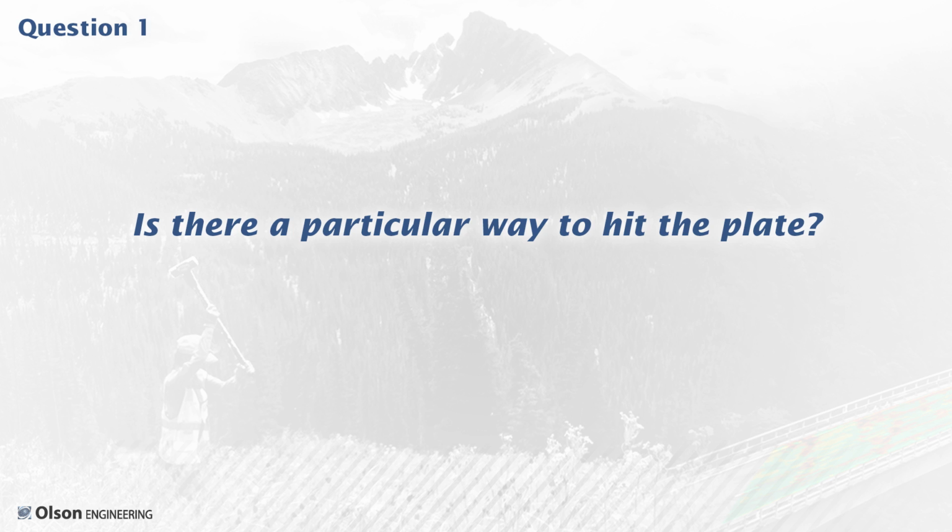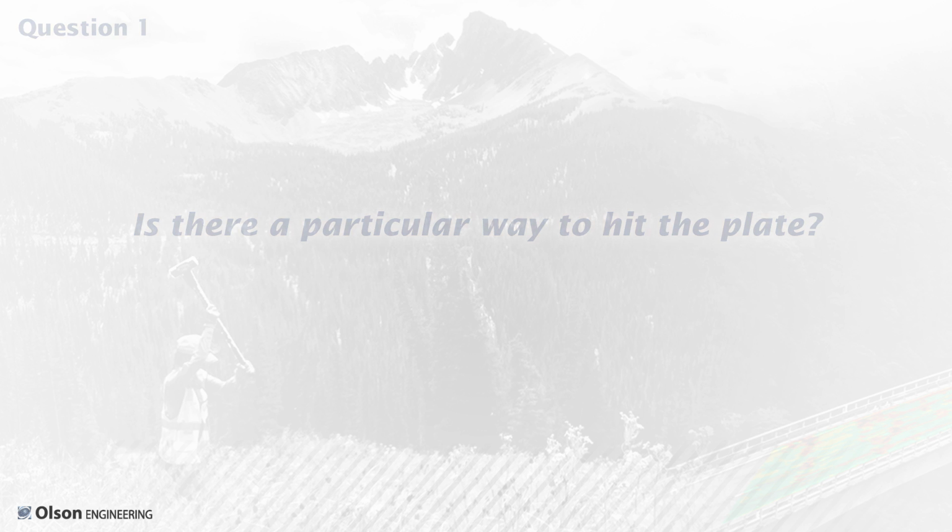And the reason why we try not to bounce the hammer is oftentimes when we do refraction surveys, we're also doing MASW surveys. So if your goal is to use your seismic data set for both, you want to hit the hammer as vertically as possible with one clean hit. After the hit, you try to catch the hammer. There are other things that are helpful, like at Olson Engineering, we make these custom plastic backed aluminum plates. The plastic really helps with the coupling with the ground, and also helps with bounce. And since it's aluminum, it's a little bit lighter.